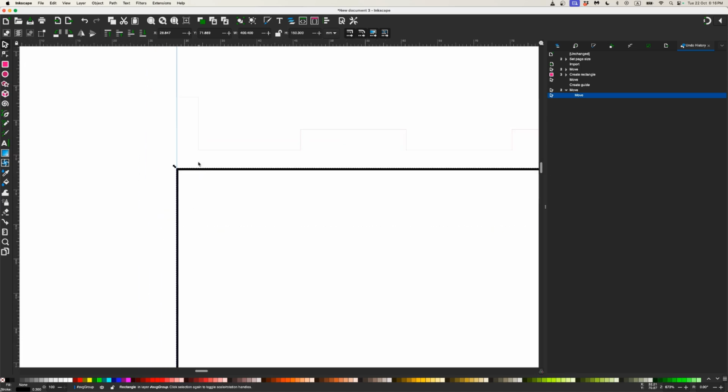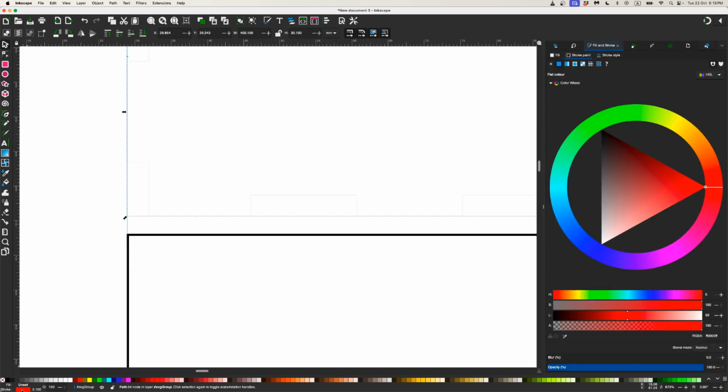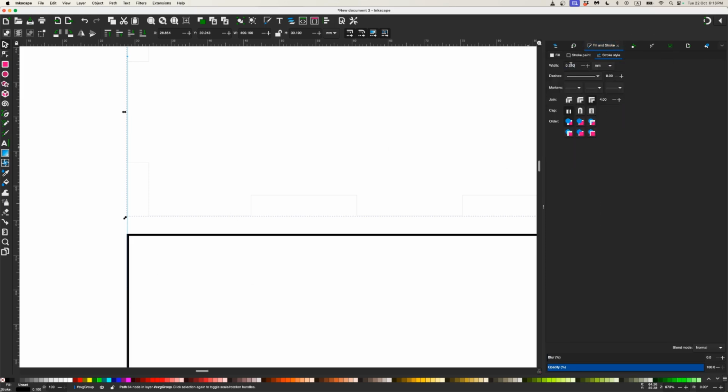I'm going to set their line thickness to the same. So see how those lines are really thin, they're really thick? We can change that. I'll just select this top shape here. I'm going to click on this bit that says stroke down here. I'm going to set it to black, and I'll click on this number down here, and I'll put that to like 0.3, and may as well put this one also to 0.3.